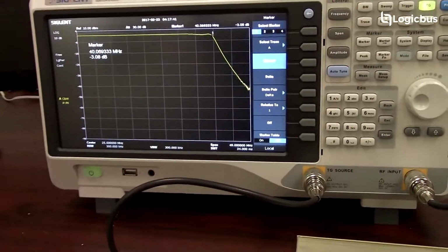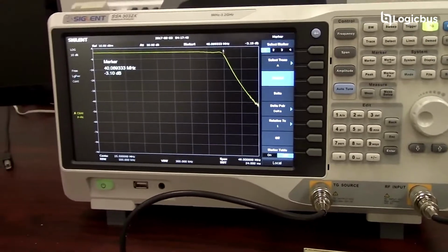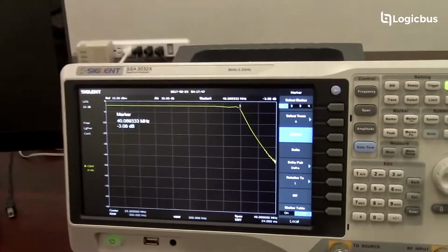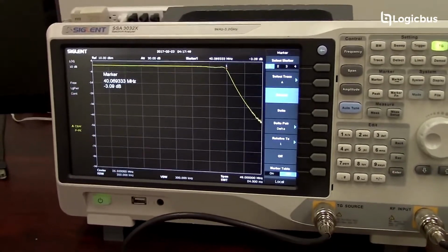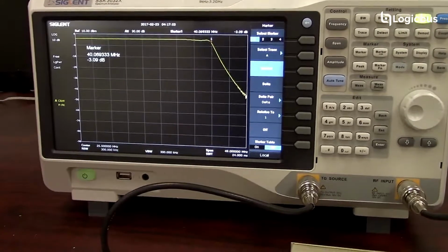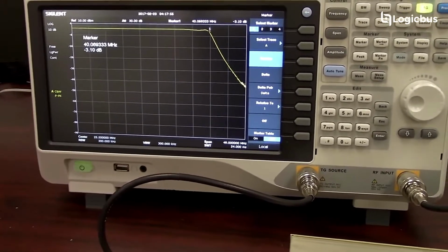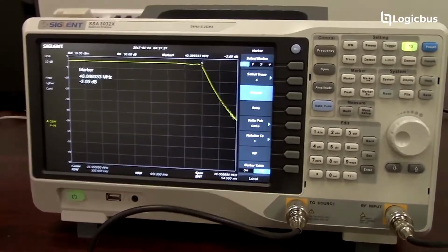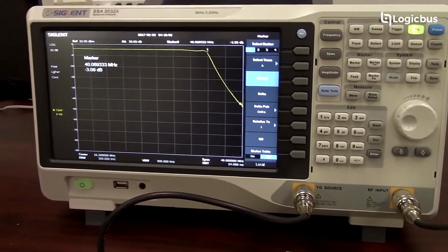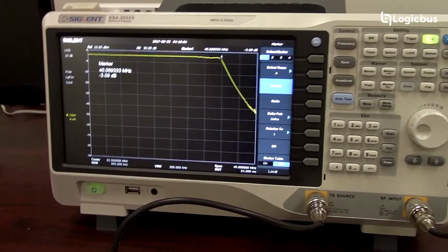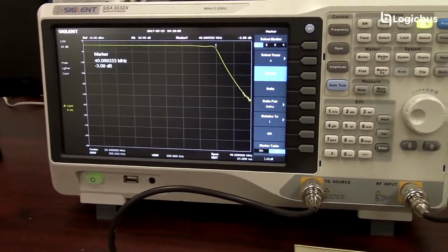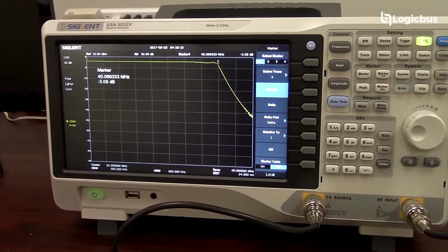The advantage of using a tracking generator with a spectrum analyzer is that the measurement capabilities of a spectrum analyzer are significantly better, with a much lower noise floor and higher sensitivity than with an oscilloscope. But to do basic measurements on a filter, be able to characterize it, or if you have an unknown filter, you'd be able to get in the ballpark, so to speak, using the oscilloscope and arbitrary waveform generator. So it costs a little bit less. It does have less capability, but to get in the ballpark, it will get you there.